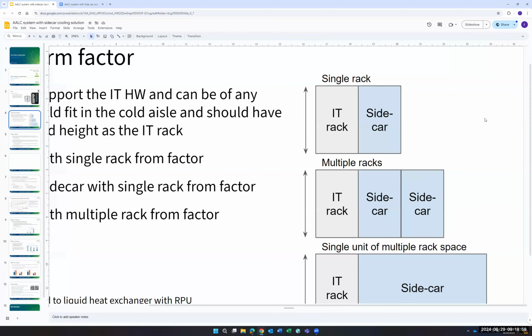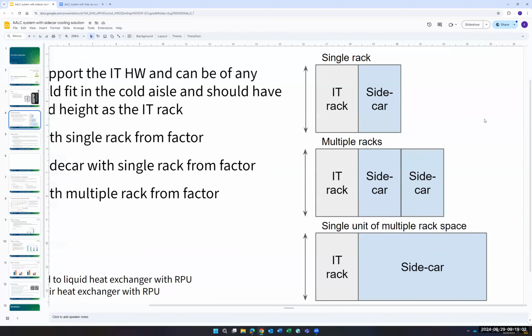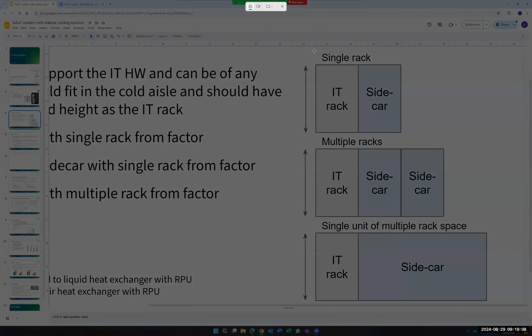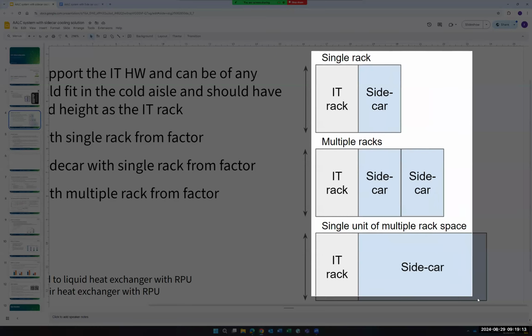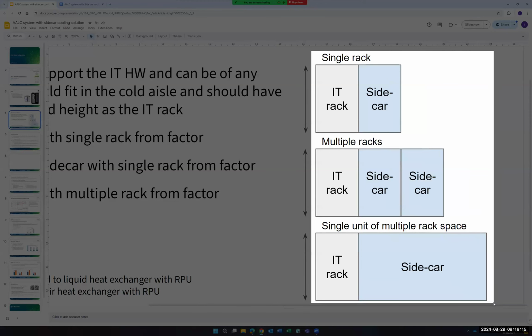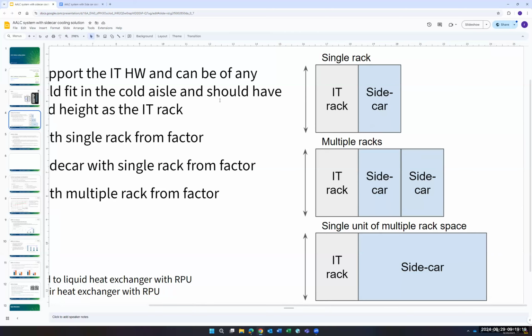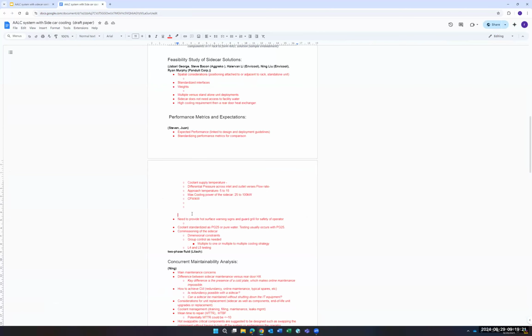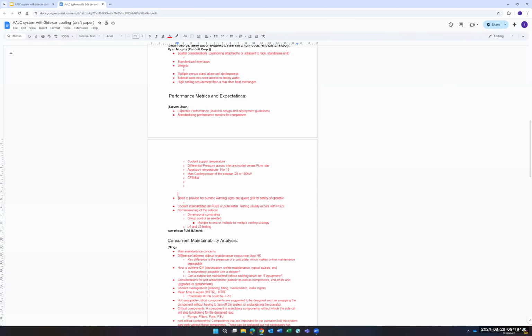So if you use a rear door and you want to move a lot of air through the servers, which are prepared for liquid cooling and not for air, then you have to move a lot of air through the servers to be able to cool down the water in the rear door. It is a really big problem, because this equipment is designed to be cooled by water, not by air. So there is no space to move the air through the servers.